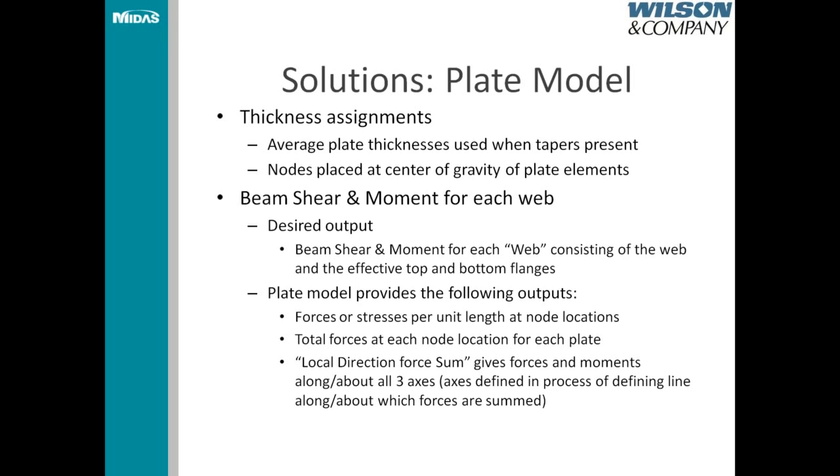In terms of thickness assignments, the average plate thickness was used when there were tapers. Nodes were placed at the center of gravity of all plate elements. The output that we were looking for was beam, shear, and moment for each web element, which consisted of the web itself and the effective top and bottom flanges.